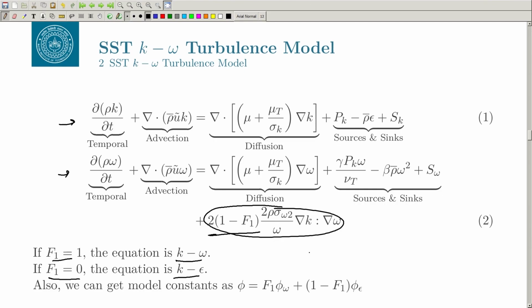One thing I am not explaining: I have been using this term gamma. For now you can take gamma equal to 1 for all this flow. Gamma is a representation of intermittency, which I will talk about very soon, maybe today or in the next class. It is like if you have a boundary layer, which is basically laminar, and that becomes transitional and then becomes completely turbulent.